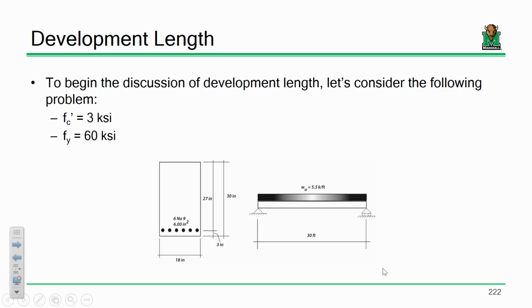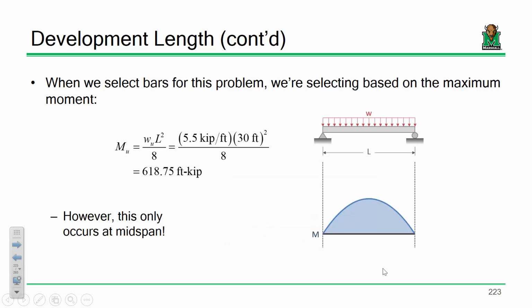Now here's the thing. We've been using that formula for moment because it does reflect the maximum bending moment. Go back to basic statics or structural analysis, and you have a simply supported beam with a uniformly distributed load. And so you're right, wL squared over 8 tells you that's the bending moment at midspan. That's the point I really want to make. That's the moment right here.